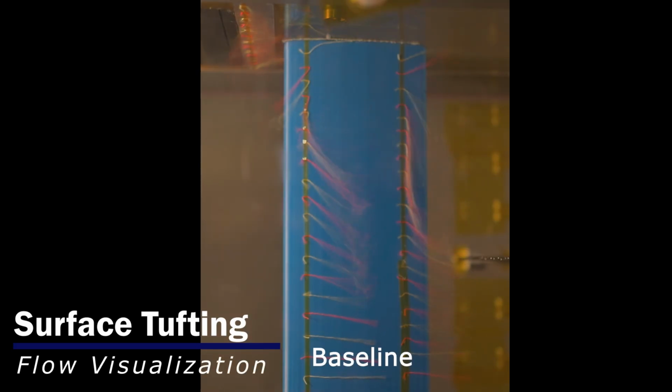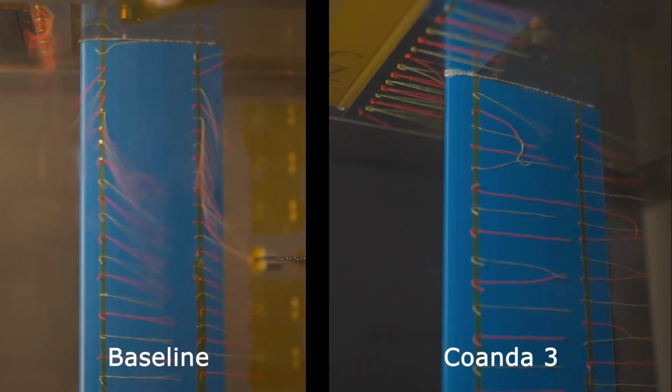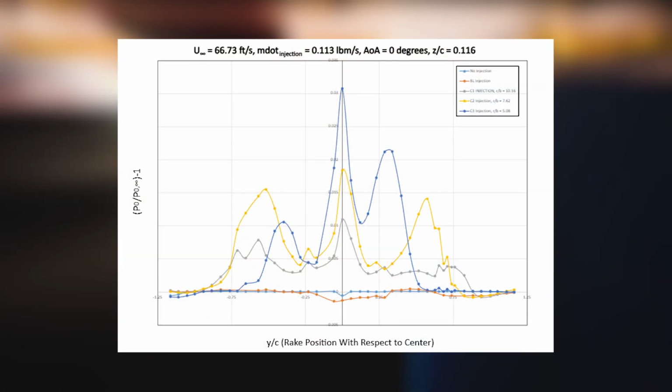The baseline injector case shows chaotic and turbulent behavior as the leakage air impinges the main flow. Coanda Surface 3 causes the flow to remain straight and attached around the stator, which is a product of fluid entrainment. The following total pressure data was taken at the same operating conditions.